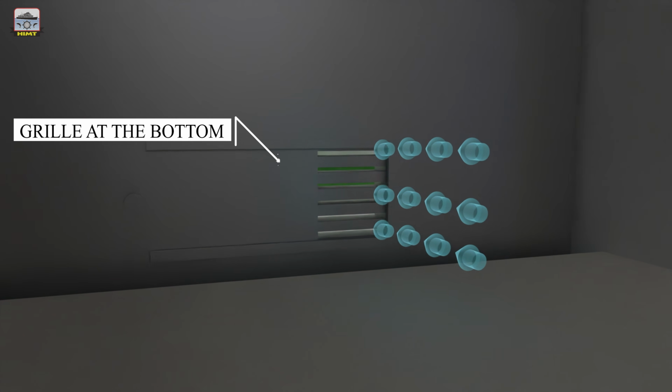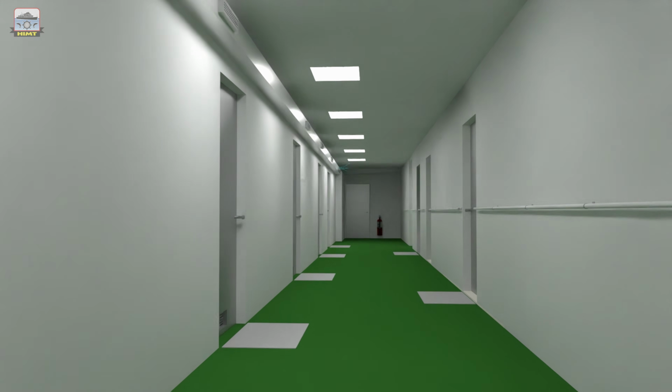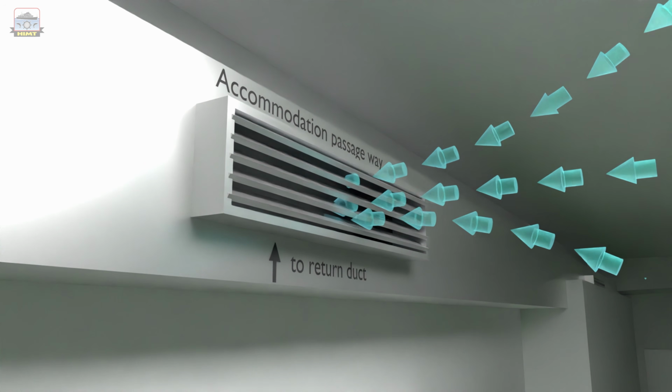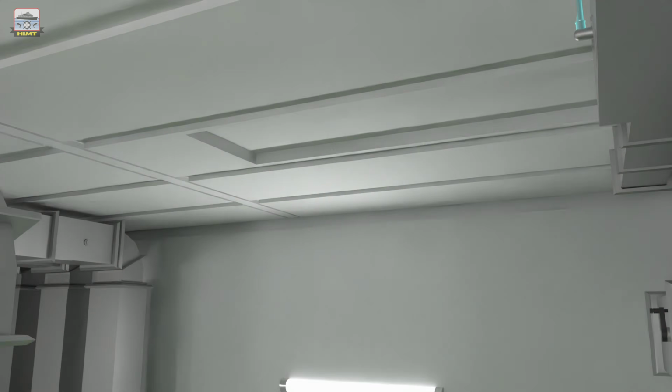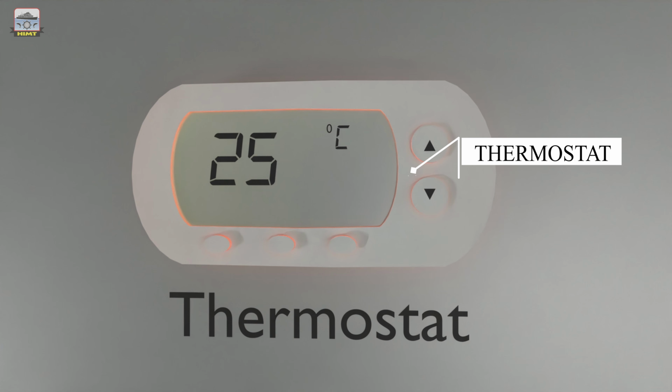Approximately 85% of the air entering the room passes into the passageway through the grill provided at the bottom of the main door. The return air duct picks up this air from the passageway, carries it into the air handling unit. Additional measuring instruments fitted in the system to facilitate optimum functioning are a thermostat at the return air duct, which acts as a control hub to start or stop the heating or cooling system for the air.